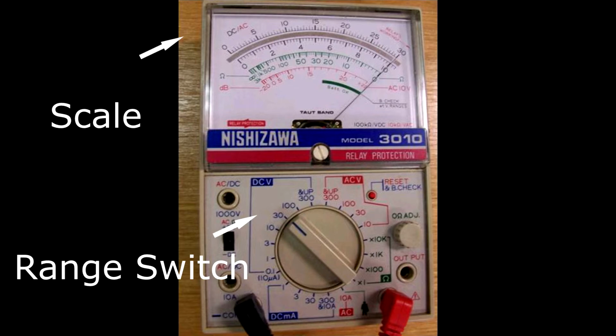But say that the volt range was set to 10, you would read the lower blue scale as the full range. Also, say that the range is set to 100. Since this meter doesn't actually go up to 100, you would use the bottom blue scale, that is at full deflection at 10, and just times it by 10 to get to 100. So say that it got to 4, you would have to times that by 10 to get your correct reading.